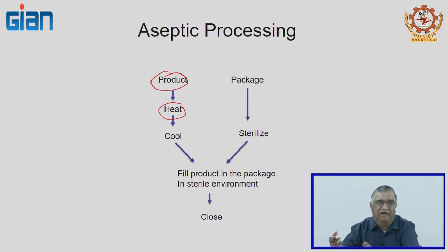One of them, for example, is the tubular heat exchanger, where you pump the soup through a central tube, and then you have an outer tube where the heating medium can pass through, thereby heating your soup. Or you can have a scraped surface heat exchanger, where you have a similar mechanism, but also an agitator which mixes the soup as it's being heated.